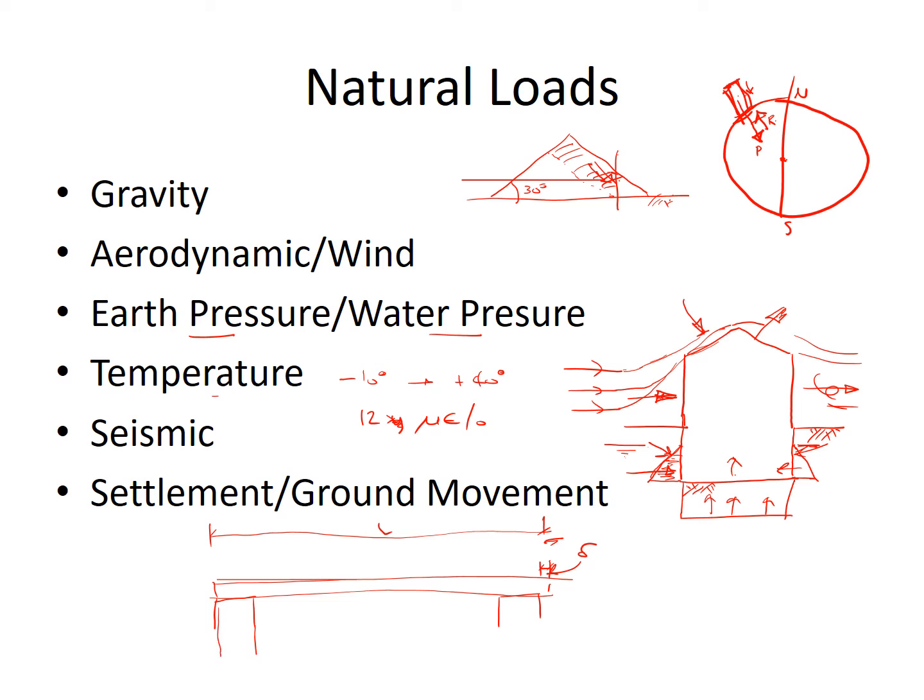And the problem that you've got is let's say that delta is 25 millimeters for a bridge deck that we might be designing. That bridge deck is trying to expand by 25 millimeters. Now, the forces that are involved in that expansion, if you try and resist that expansion, are phenomenal.